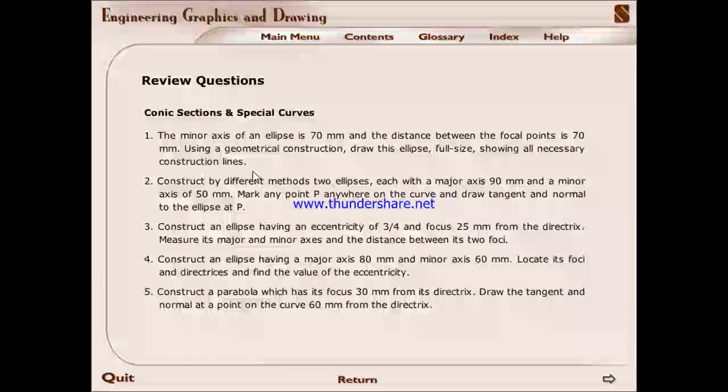Third question. Construct an ellipse having an eccentricity of 3/4 and focus 25 mm from the directrix. Measure its major and minor axis and the distance between its two foci.